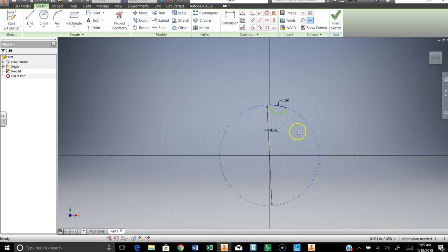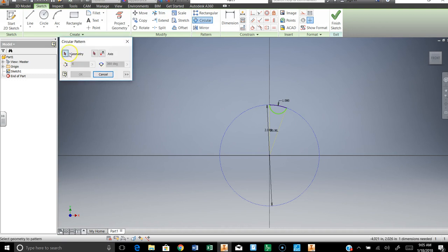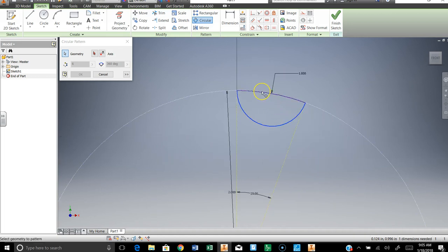Now, we're going to use something called the circular pattern. You've used it before. We're going to use it here. We're going to say circular pattern. And the first thing it's asking me for is what do I want to make my pattern out of? It's this arc, and now, I'm going to hover here. Just wait. Because right now, it's selecting the constructed circle. I don't want that. If you wait, I'll get a little drop-down menu. I don't want curve 1. I want curve 2, the piece of the arc. Let's click that.